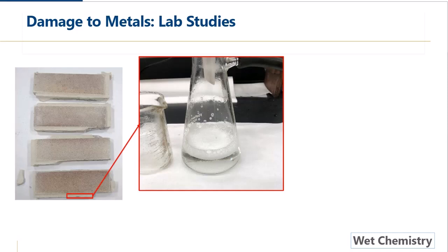And so the chemist who is doing this has been doing this for quite a number of years. And when she saw this, she snapped a picture and said, "This is not normal." So what we have here is this flask contains the water from that water extraction where it's been filtered down through a filter that you can't see in the photo. But she said, this is foamy. This is not normal. This is not what's expected. And that foaminess is an indication that there's still residual detergent from the cleaner in that mortar. So all of the cleaner residue has not been rinsed from the building. It is still there and can still interact with surrounding materials in the event of rain.